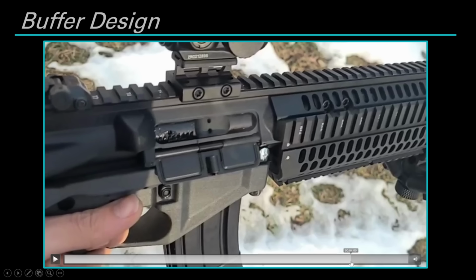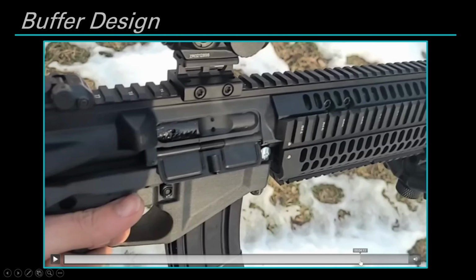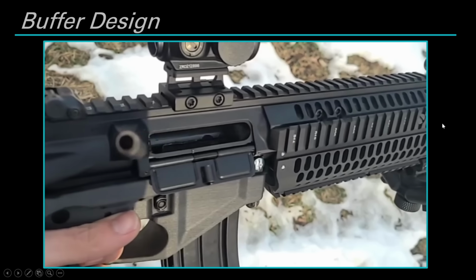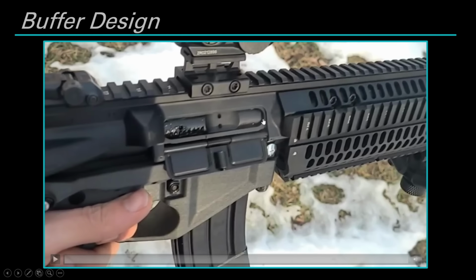As we see if we continue frame by frame, about here, the hammer has just now smacked the bolt carrier while it's retracted. And while the hammer will then quickly shut the bolt carrier like that, that doesn't have enough energy to fire the next round, and we see that the gun doesn't fire. The trigger would be dead, and the rifle would need to be manually racked in order to get the gun working again. Just to show you guys one more time, the round fired, the bolt closes, the bolt bounced, the hammer drops, and then the bolt slams back forward.